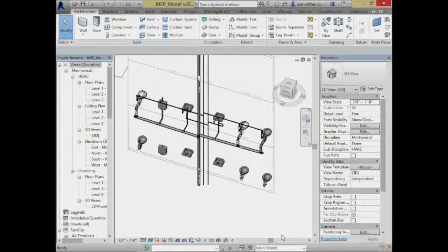In fact, there may be several different systems. There may be a designer who does just specifically the plumbing systems and how the sanitary sewer system works. There may be a very different designer who's actually doing the sprinkler piping, okay, and has responsibility for that. And the principle that we try to use is that everyone should basically have control of their own file, but not be able to change pieces of other designs that they aren't ultimately responsible and liable for. So what we tend to do is create lots of separate files, and we just link them together. We can pull them all together based on the same XYZ coordinates. So we can coordinate our work without giving you the ability to change someone else's work. Okay, it's much, much cleaner this way.